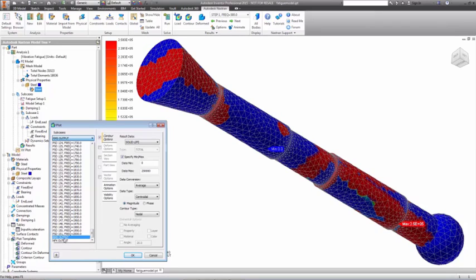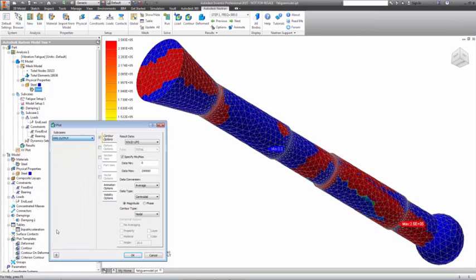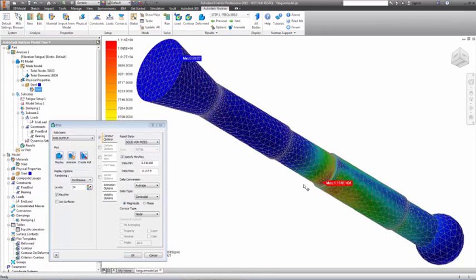Finally, you have the NPX, or net positive crossings, which are the pseudo-frequencies that represent the equivalent frequency the fatigue life was based on. So while the goal of this analysis was simply the fatigue life, a whole set of other useful information about the structure is produced along the way. Random vibration fatigue in Autodesk Nastran InCAD provides engineers with long-term insights to a product's robustness and dynamic behavior.